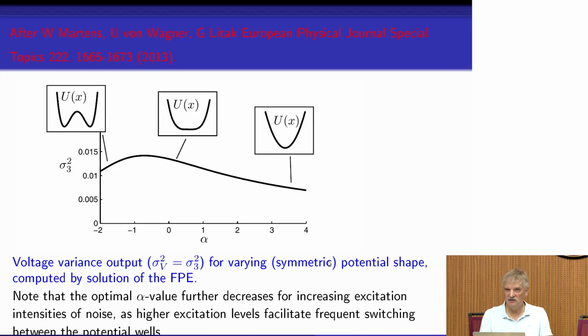So this result is also consistent with the statement that you have two effects. One is enlarging the amplitude of oscillation, because the potential is for the mechanical system, and you can expect that if you have two potential wells, you have a larger distance between the equilibria, so this could be a larger response in amplitude. However, you should remember that if you produce such a barrier, then you need stronger excitation.